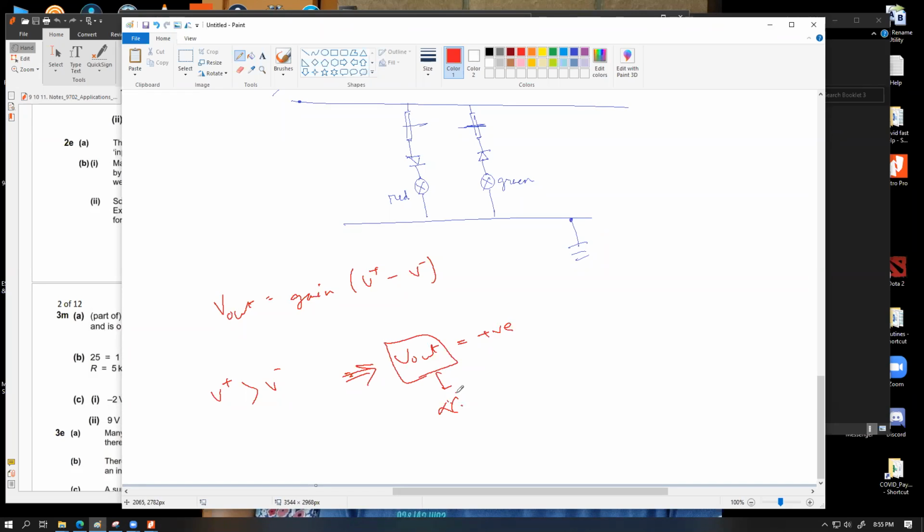So let's say alpha percentage. I'm just writing this as a basic variable alpha. It doesn't have to be, it could be anything. We're gonna add a positive fraction of output voltage and we're gonna add it to the V minus, whereas the symbol before the V minus is actually negative, which means this positive fraction of the output voltage is attached with the V minus input. So it's connected to the inverting input, or it is out of phase. So for a positive voltage, you are providing a negative feedback because you're connecting it with the V minus. That's one way to go for.